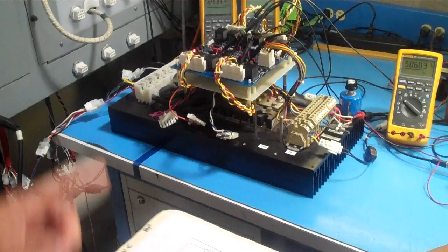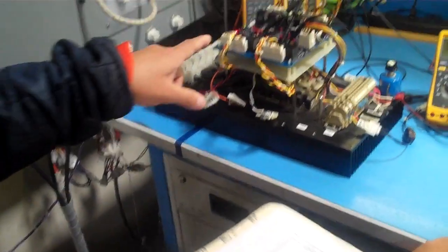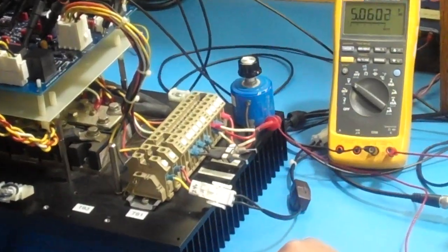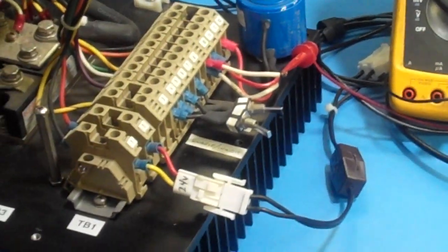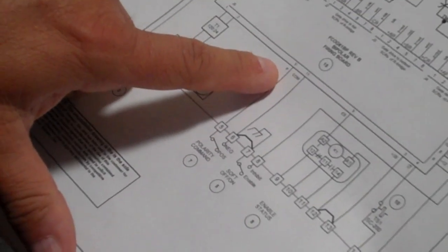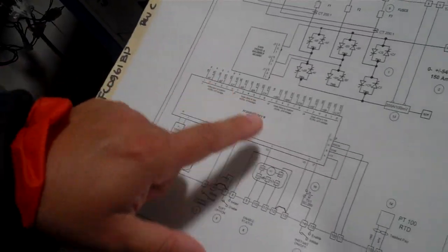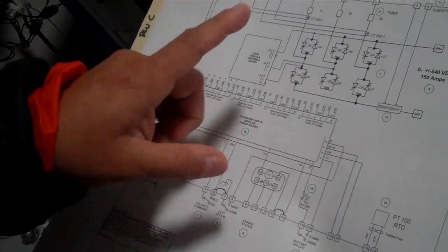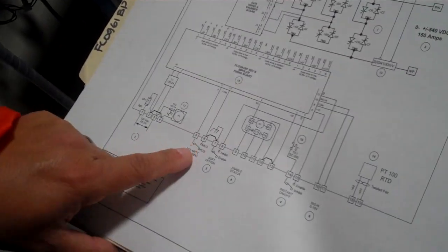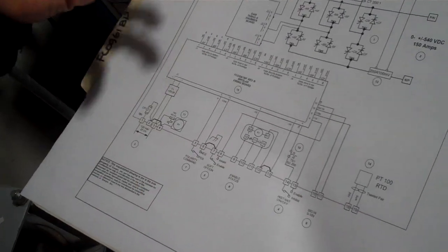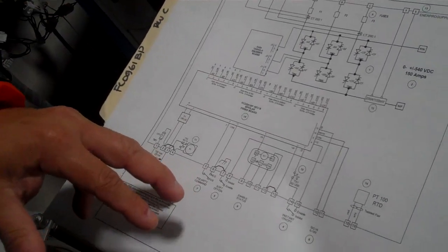So what we're going to do is we have a switch. Can you show me the polarity switch? Yep. We have a switch that will either bring this P signal that is normally pulled up down to ground, or we're going to open it to let it go back high. Every time that P is high, the board fires in the positive direction, and when we close that switch, P goes to common, and the bridge now fires in the negative direction.